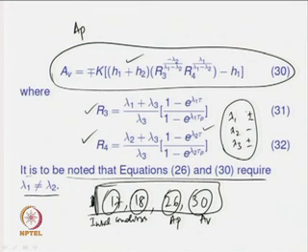For identifying a stable second order plus dead time transfer function model, you pass on a negative lambda 1, and similarly lambda 2 has to be negative, and lambda 3 can be either positive or negative depending on what type of zero you have. It does not matter, but care must be taken to pass on negative lambda 1 and lambda 2 values.